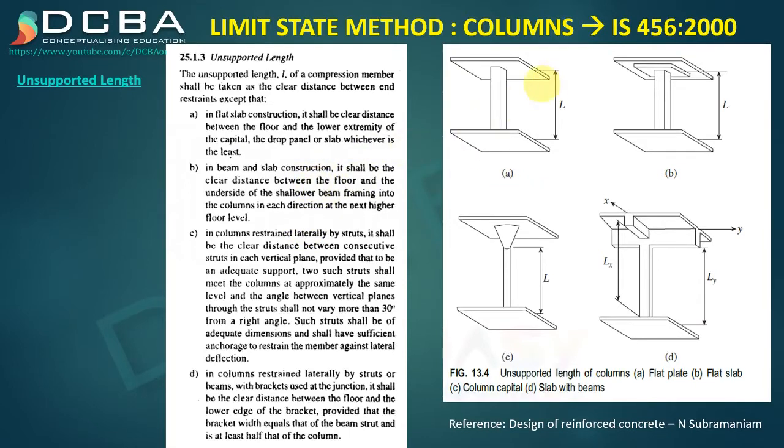So basically this first image that you are seeing is an image of a flat slab. Now flat slab, this term must be new for undergraduate students. Flat slab is nothing but the system where you completely eliminate the beams. So there is only slab and there is column. There are no beams. The slab itself is well reinforced and it is able to support the load. This is a new modern kind of technology, and in a lot of places this flat slab construction is used.